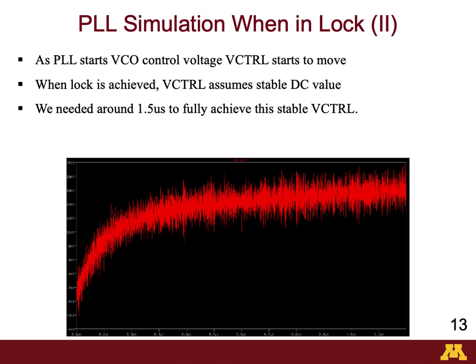As the PLL starts running, the VCTRL moves up from the initial 0 volt, and after some time it gets almost stabilized at some higher voltage level and doesn't move from there. Now this is the ideal condition. Both inputs of the PFD have exactly equal frequency and a small yet constant phase shift between them.